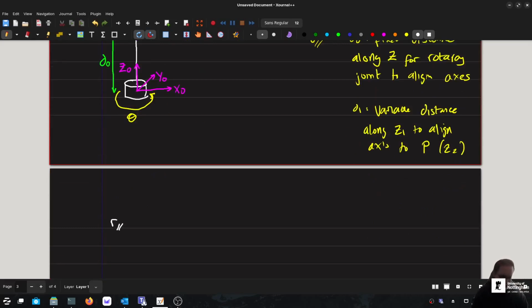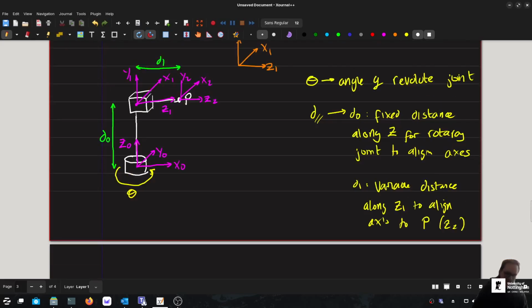Now, there is a video in the lecture slides I have added to the Moodle page. If you go right to the bottom slide, there's a video that explains this a little bit more, because if you've got twists in your robot, this will be a bit different. However, we are doing the simplified version of the DH algorithm here, whereby for this course we can assume that the distance along the common normal is usually just the distance along the x-axis. There's a reason why I typically set x to the right at the beginning, because that's the flow of our robot in that direction.